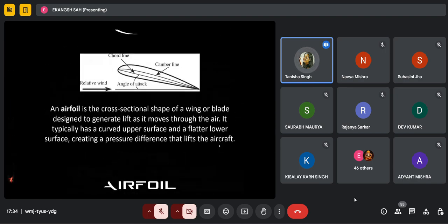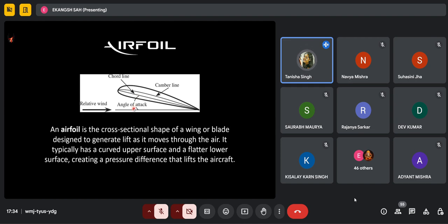An airfoil with lift also has an angle of attack, as shown in the figure. The relative wind is the direction of the wind at some distance from the wing. It is parallel to and opposite to the direction of motion of the wing. The velocity of the relative wind is equal to the speed of wind. In aeronautics, the geometric angle of attack is defined as the angle between the mean chord of the airfoil and the direction of the relative wind.